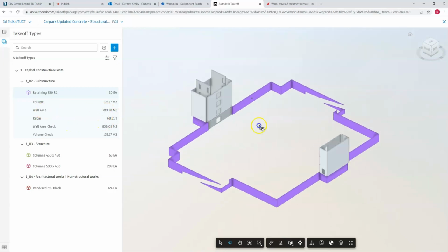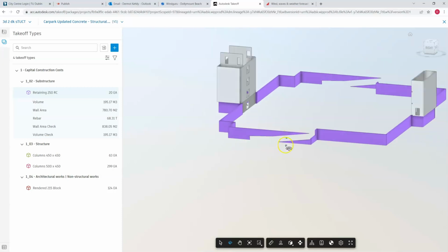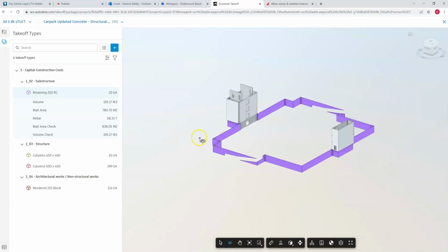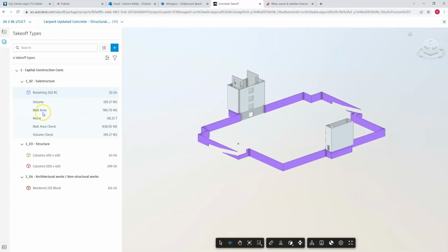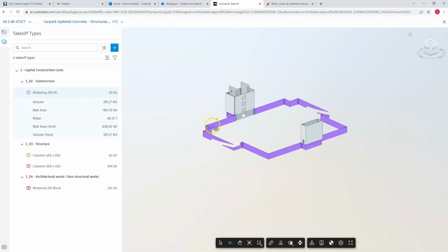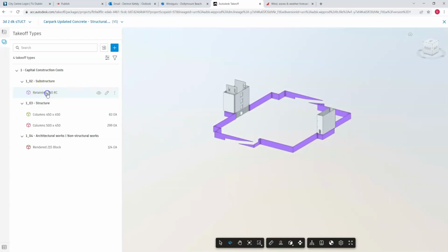And maybe some of you realize what the difference could be. Well, it's these gaps here. So if you take the length of that wall times its height, you're measuring through those openings. And that's why there's a difference between the way it's measured from a length to height point of view versus the object properties that omit the openings from the wall area property map. And that's essentially the quantities from our retaining walls.